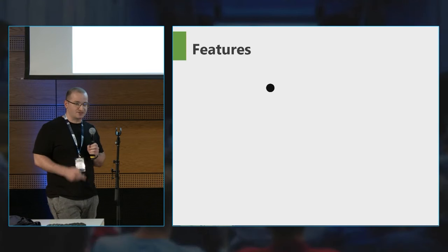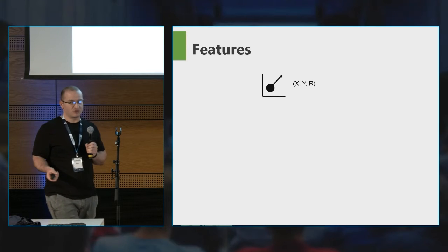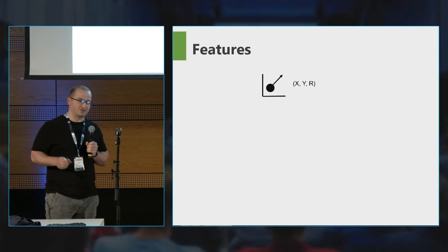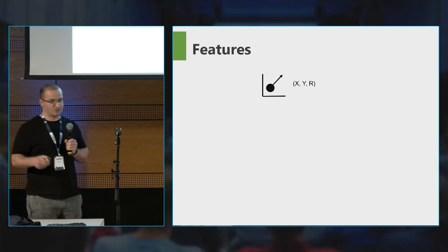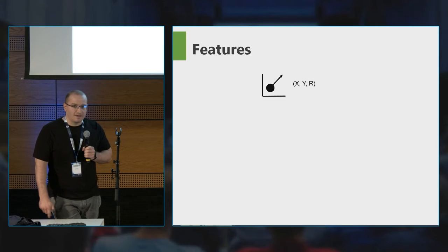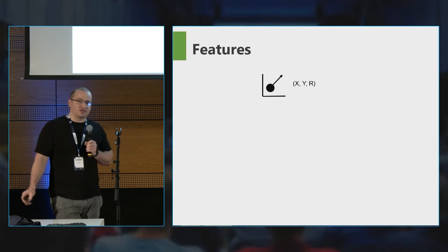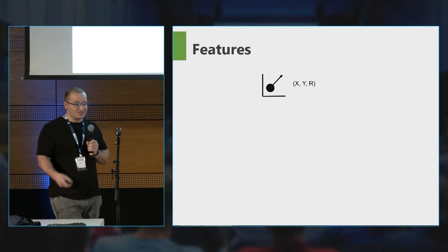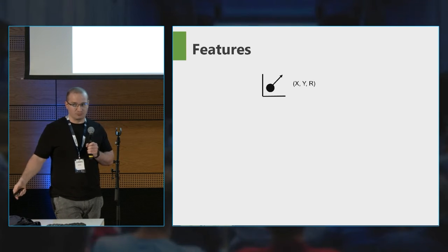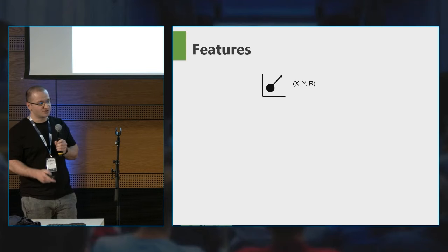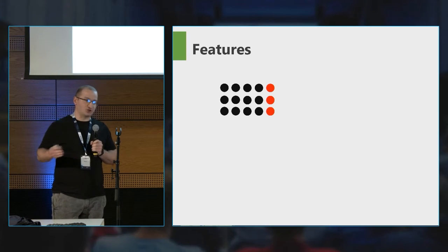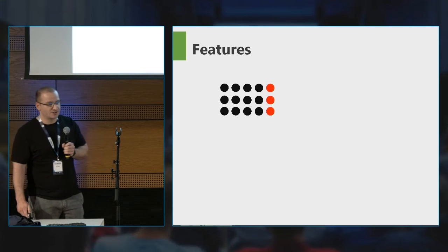So in this context, a point is the usual xy coordinates plus an added rotation r, because keycaps are usually not independent of rotation. So as well as the position, you need the orientation of the keycaps. Now, for minor, easier projects, it could be viable to just simply list x, y, and r coordinates to lay out your points, but Ergogen makes it easier for you by using zones which are made up of columns, which are in turn made up of individual points.